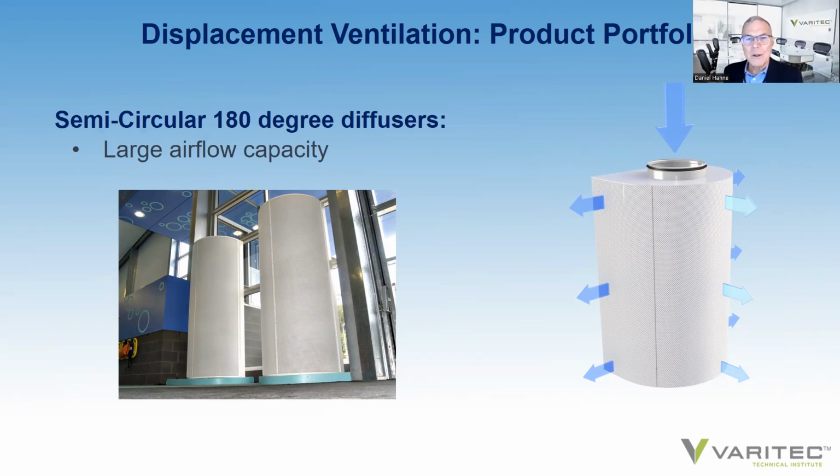There are also 180-degree diffusers, 360-degree diffusers that are used to create full columns in large open areas. And it begs the question, if you do have a large open dining area with 15 feet ceilings, is it really necessary for thermal comfort to provide 75-degree air at 12 feet above the floor? That's a lot of energy to maintain that uniformity of temperature in spaces with large ceilings.